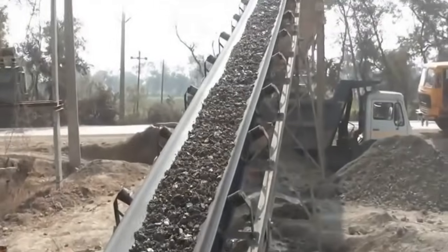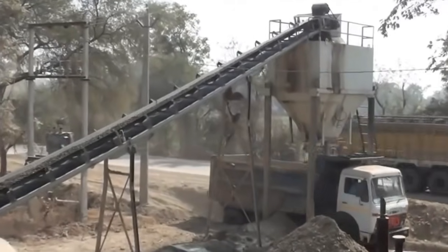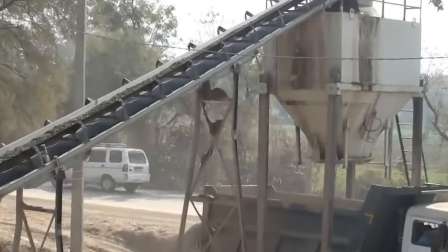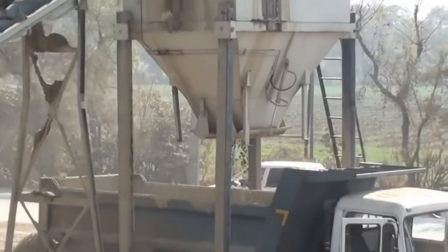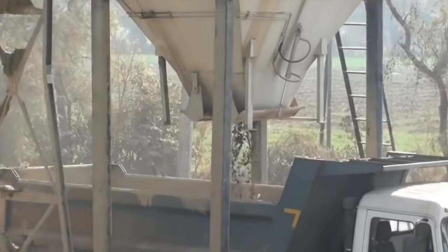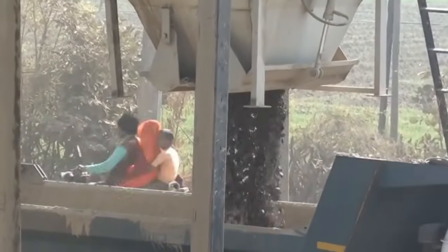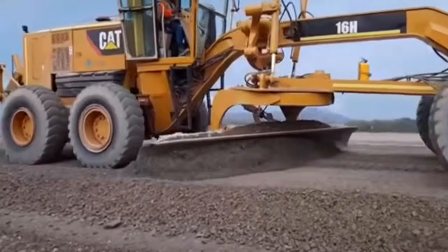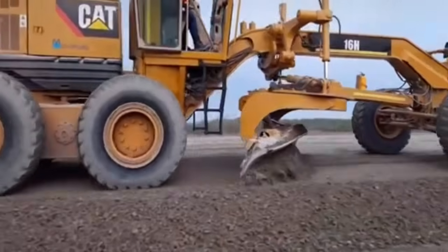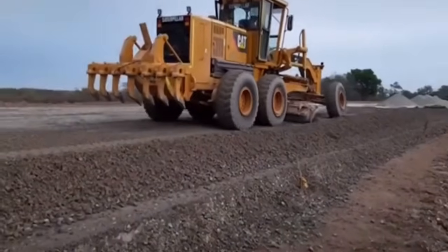Considering the compaction, the loose laying thickness shall be kept 15 to 17% extra. For compaction, the test trial shall be done to check the number of passes required to achieve 98% of relative density. The passes shall be made as: at the beginning 1 plain pass, then 2 to 3 low vibration passes, and at the end of compaction, again 1 plain pass. The speed of the roller during compaction shall not exceed 5 km per hour. Generally, high vibration passes are not used in Wetmix because they may crush the aggregates, which may reduce the durability of the pavement.